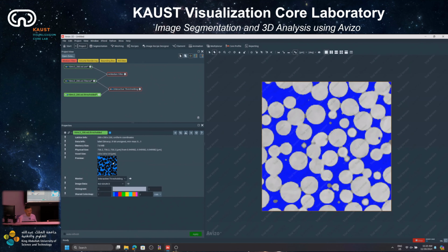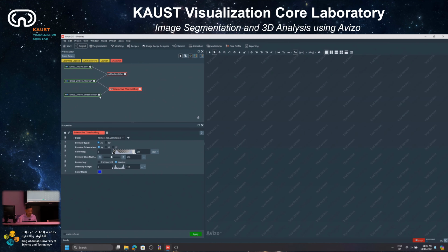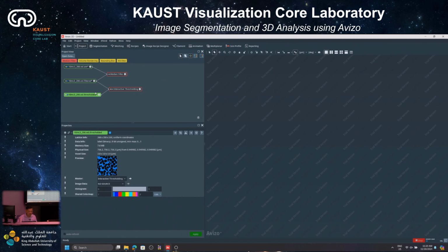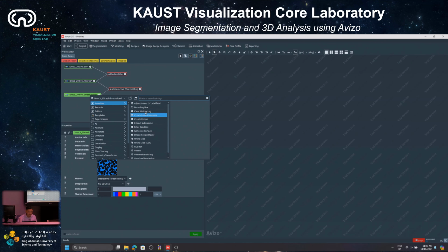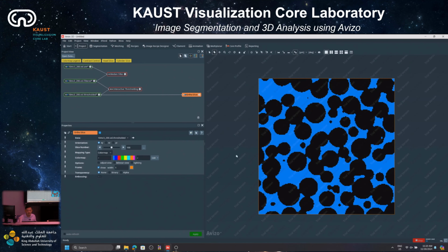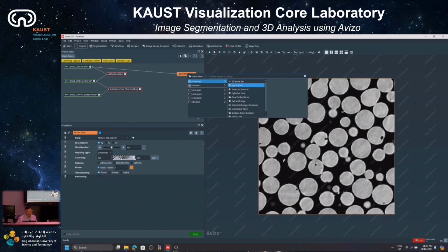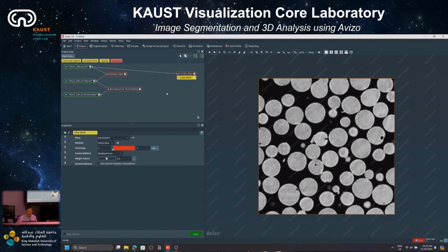Now I get to see the result of the pore space in blue. If you turn off the visibility of the interactive thresholding module, you can directly visualize it with the auto slide of this data. The previous is similar to the PNM step. Again, if you would like to visualize it using the original data, overlay with color wash, right click, color wash, and data.